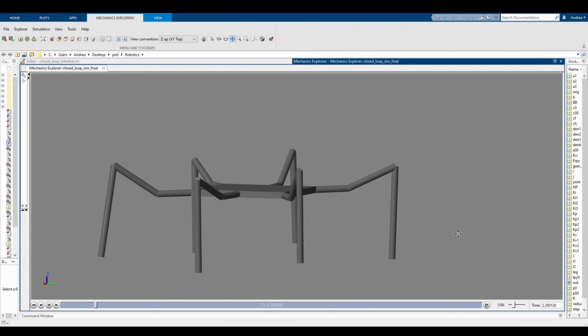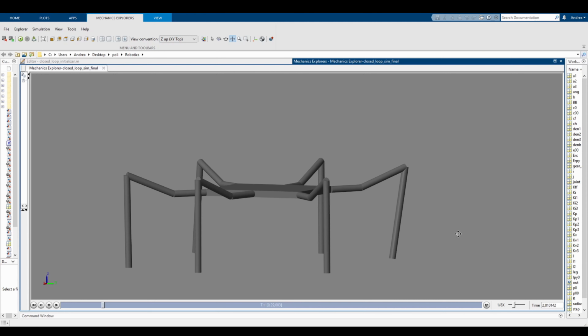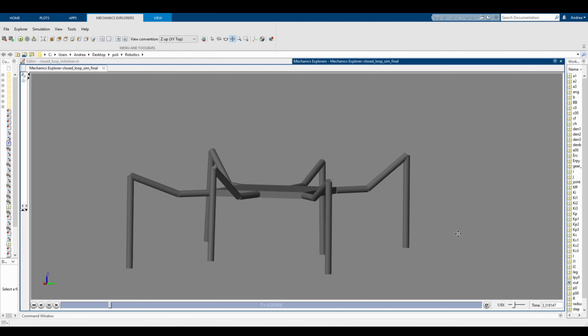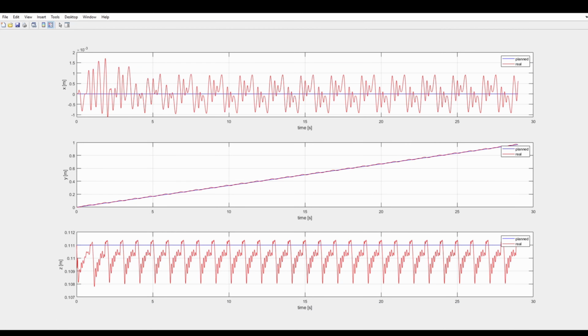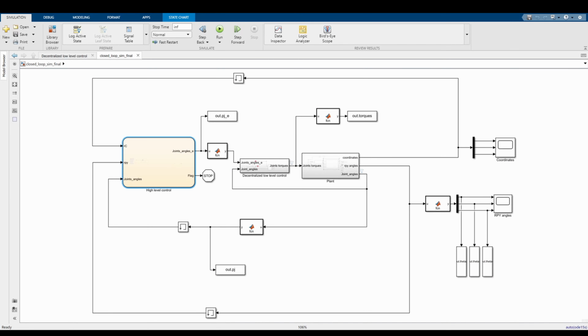The real pose and joint angles are sampled, so that the real positions of the legs required to stay in place can be determined and used in the computation of the expected trajectory in the joint space. By taking into account the real pose of the hexapod, the unavoidable errors in the task space trajectory can be kept within acceptable bounds. To control the system, we have chosen a decentralized control system based on two levels.